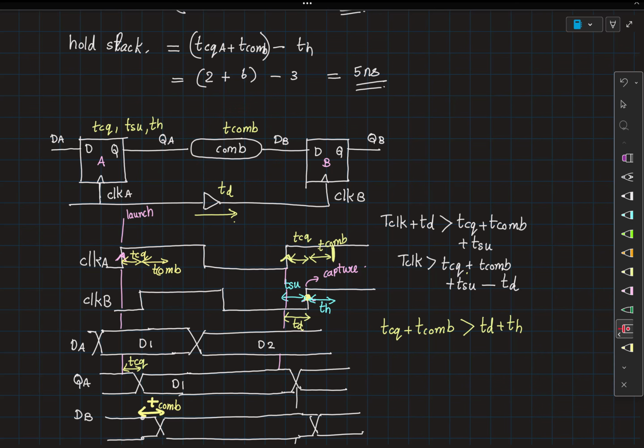Right? Now during the design phase, let's say your hold constraint is not met. Then what can you do? Then you can increase the combinational delay here. Okay. So during design phase, hold is something that you have to pay special attention to, because if you are not able to fix it during the design phase, your chip is gone. Right? If it is setup, ideally you should fix setup issues also, but at least you have some leeway after that. Okay, so we can have the quiz now.